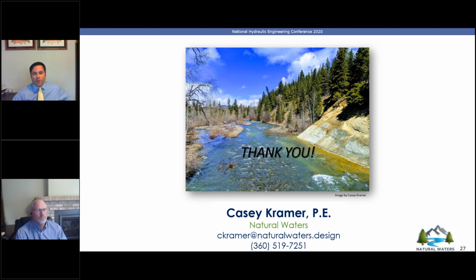Okay, so those are all great points because that's probably what's going to happen, guaranteed, especially when you're dealing with some of these models that are from the 1970s and 80s. Now, what I'll say to that is that even though the discharges and the topography from the effective model may be old, you're still going to be able to utilize one 2D model for the analysis. And that's really going to come from the development of your corrected effective model.